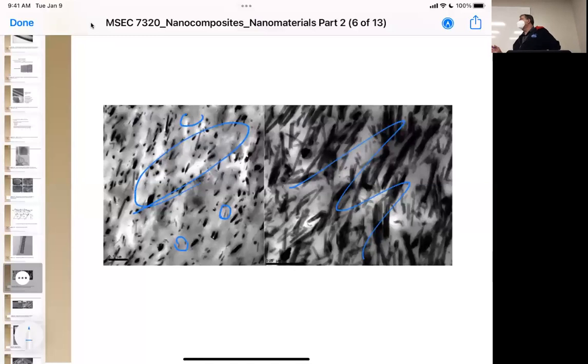So the fact is that you have only the one long axis and the two small axes, which lowers the viscosity problems, and you actually get a better dispersion with lower shear processing. Okay, does that make sense why we can have lower shear processing from this system? Because there's less interaction between the inner surfaces of themselves, and they easily disperse, and now they're interacting with the polymer matrix itself. Okay.